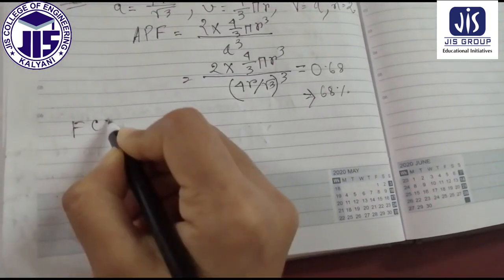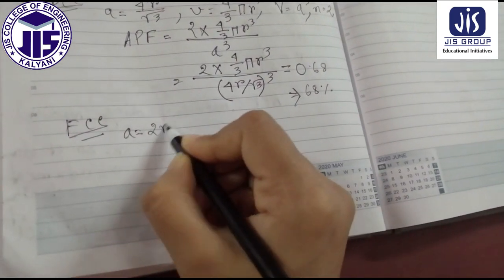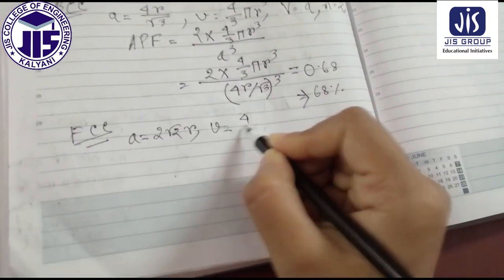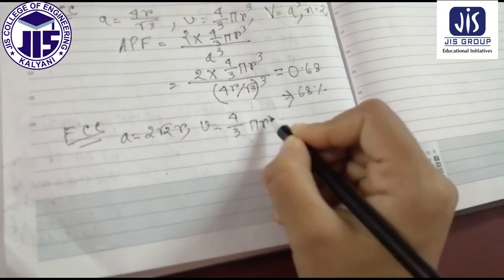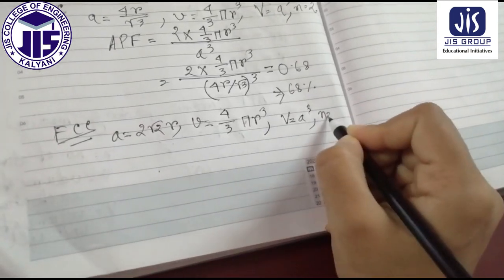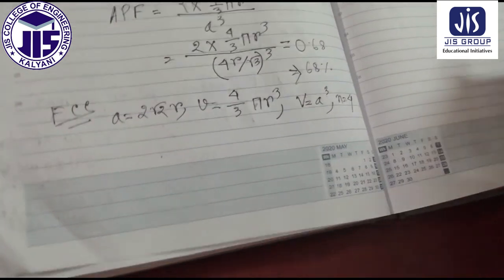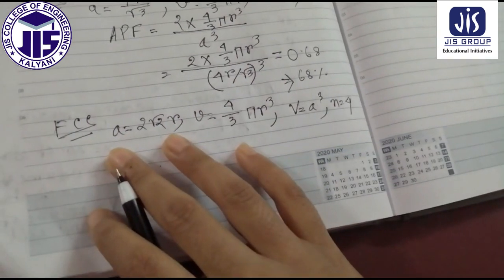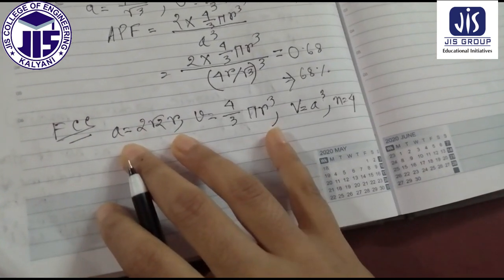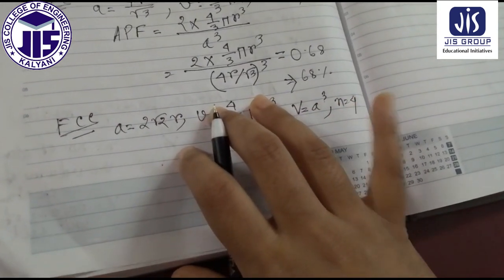For FCC, the relation is a equal to 2 root 2 r, small v equal to 4/3 pi r cube, capital V equal to a cube, and n equal to 4. This is the relation between a and r.